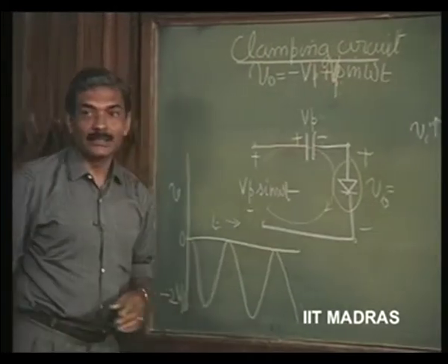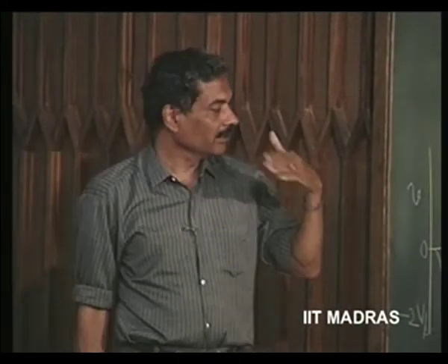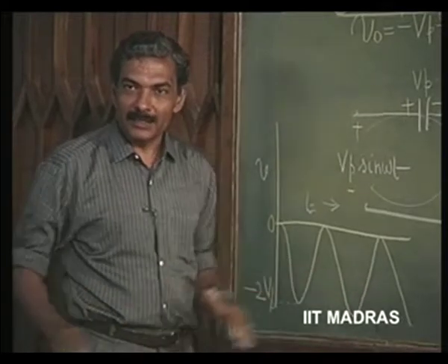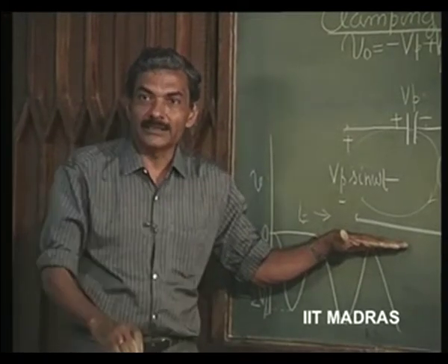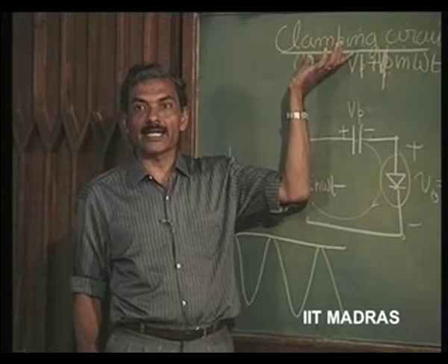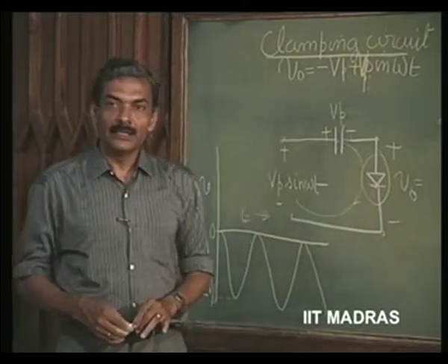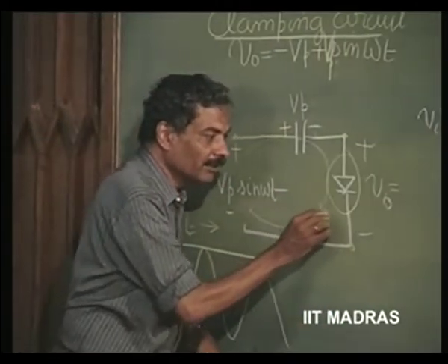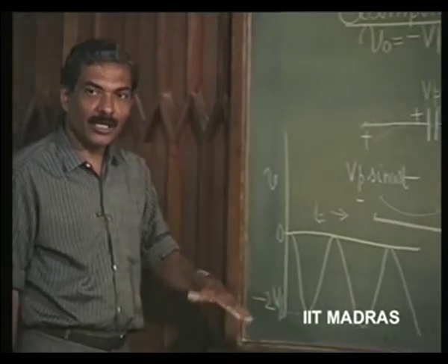This also is very important in variety of applications. Let us say in the case of a standard value of voltage for blacker than black in television application, etc., you would like a particular value of voltage to be maintained and all the voltages, let us say video signal, to go below that or above that. So, in such a situation, we introduce what is called as a clamping circuit. We can clamp it to any value of voltage. That value of voltage to which we have to clamp should come in series with the diode. You can clamp it to positive voltage or negative voltage, depending upon what you want. You can put the corresponding voltage in series with the diode. It will get clamped to that particular voltage, below that voltage or above that voltage.